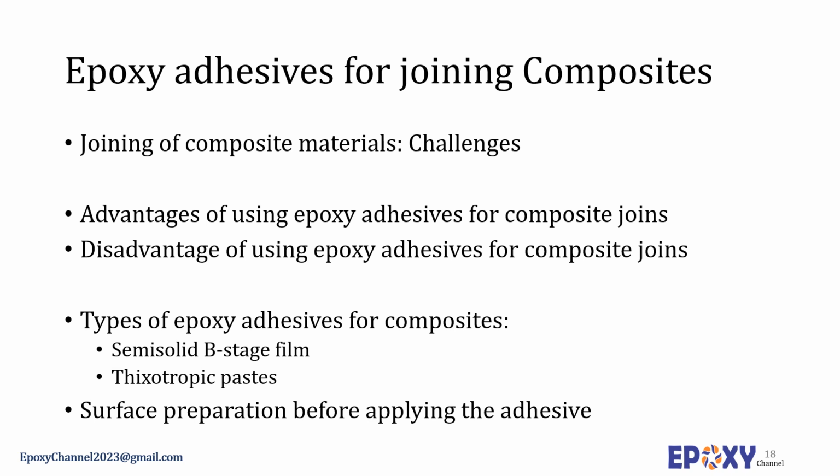The joining of composite materials involves some special problems not faced with other materials. Thermoset composites are joined by adhesive bonding and mechanical fasteners, or with a combination of mechanical fasteners and adhesives. Mechanical fasteners must be sized to avoid fiber crushing and delamination. Adhesive may also be used to bond composites. Adhesives must balance strain and flexibility.